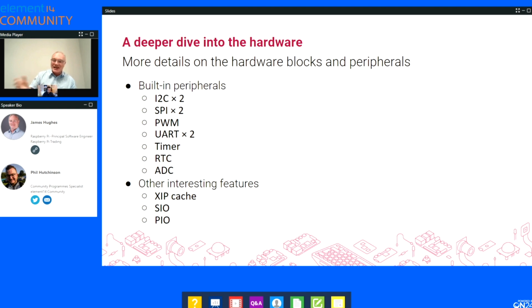So the processor can actually execute code directly from this flash memory. It doesn't need to be loaded into RAM first, hence the execute in place. Another advantage of this is that it can be cached. So we have a cache in there. You've seen it in the block diagram and on the X-ray. And this accelerates the average bandwidth and improves the latency when reading flash. It's not quite as fast as running it from RAM, but a very, very good performance boost by using the caching over the execute in place.